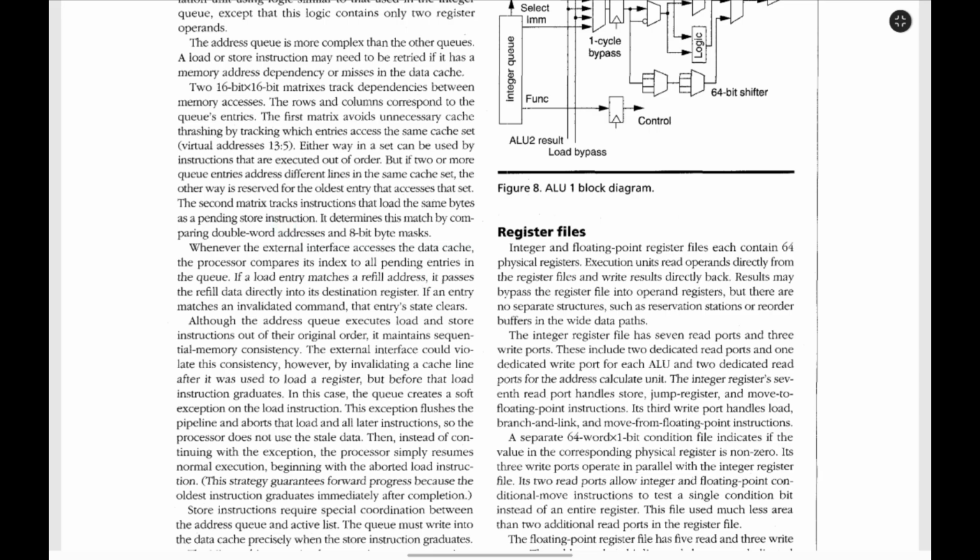Whenever its external interface accesses the data cache, the processor compares its index to all pending entries in the queue. If a load entry matches the refill address, it passes the refill data directly into the destination register. If an entry matches an invalidate command, that entry's state clears.